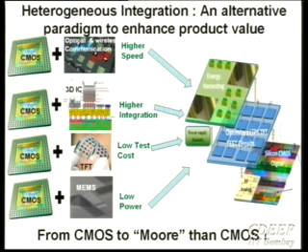So potentially what one can think of is a system, and a 3D system in this particular case, a heterogeneous 3D system. So you have the standard silicon CMOS circuits along with RF and analog. On the second layer, basically in blue, shows optimized, in this particular case, optimized low temperature polysilicon thin film transistors. These are very low cost transistors. And the idea is that, hey, if I can somehow come up with a methodology to implement test circuitries in this low cost technology to verify the underlying CMOS circuits, then I actually have a win-win situation that becomes a really low cost alternative to robust design.